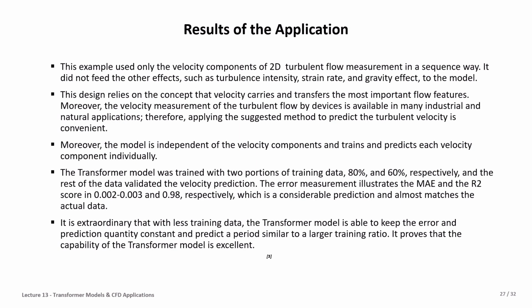This is based on the Lagrangian framework that we explained in lecture 11, how we can find the correlation between the flow properties in the Lagrangian framework and time as a time series, and feed the sequential models like LSTM, GRU, and transformer. It also works with CNN based on this idea, and then makes a prediction for this data. This approach could help us study turbulent flow for a longer period. For example, we can generate a longer period of data and study the turbulent flow, and also in some applications, making predictions will help in some industries.